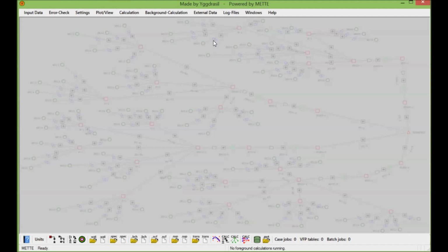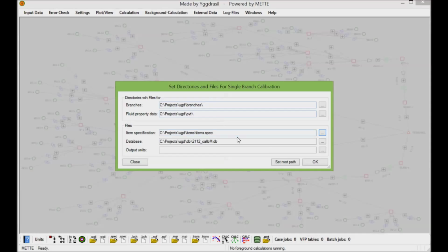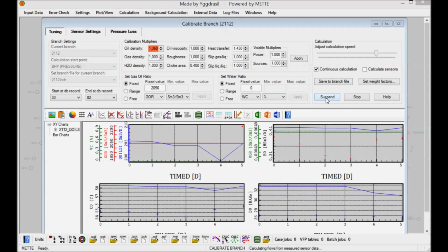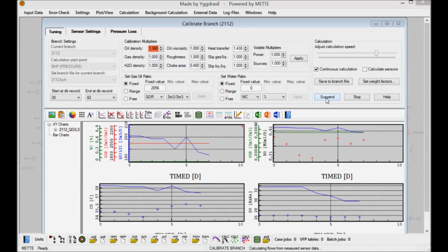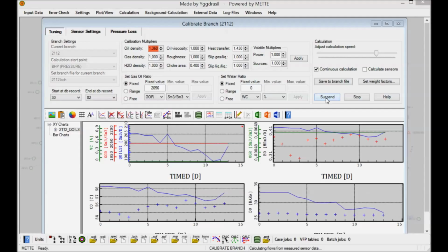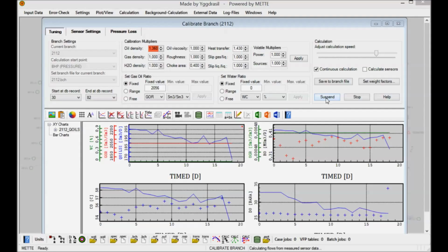For best possible results, reference data from well tests can be used to calibrate and validate simulation models. To perform tuning, import reference data to a local database. Then use the data to find the model response giving best compliance with the measured field data. Multiple tuning parameters are available for adjusting model responses. These include phase densities, gas and liquid slip factors, heat loss factor and hydraulic roughness.